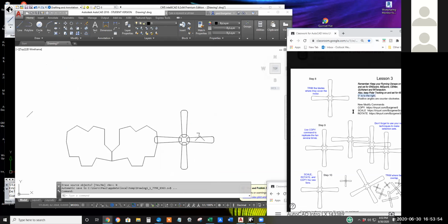By the way, the 0 degree direction is straight to the right. 180 is to the left. 90 straight up. There are some exceptions, but the general rule in AutoCAD is when you type an angle of 45, it means 45 degrees in the counterclockwise direction. That's a big deal when we get to the rotate command.